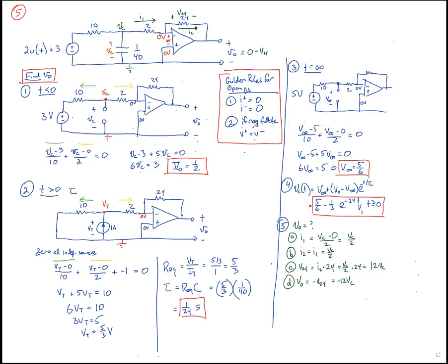So now let's just do a KVL right around here. 0 plus 0. So we're so far at, I'm solving the same thing in a different way. 0 plus V24, you hit that plus first, plus V naught equals 0. And now we're back to where we started, 0 plus V24 plus V naught. So the solution for this, if we're solving for V naught, is V naught equal to minus V24. So we found that in 2 different ways.